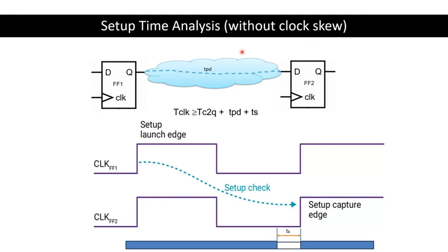So that means the timing parameters involved only include the clock period, the clock to Q delay, setup time, hold time, and the logic delay coming from the gates in the circuit. The logic delay coming from the combinational logic is denoted using the symbol TPD, the propagation delay coming from the logic gates.